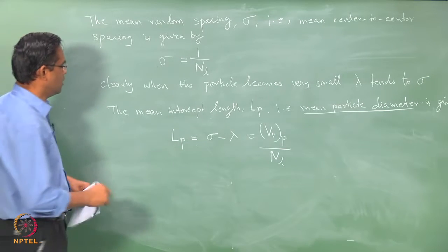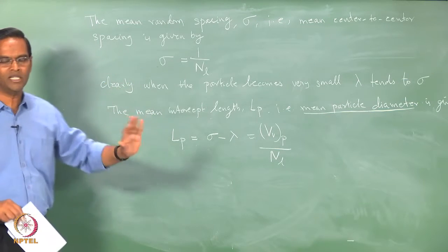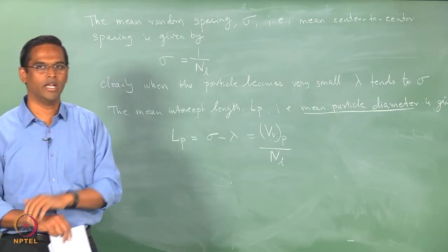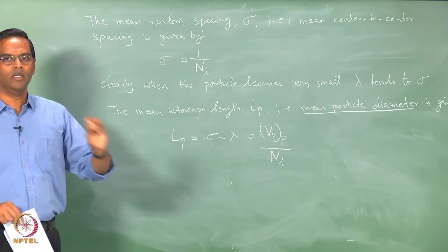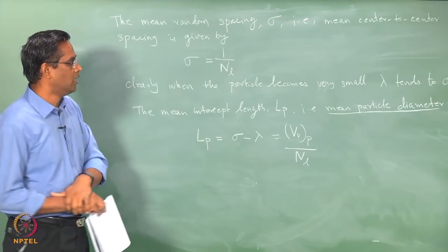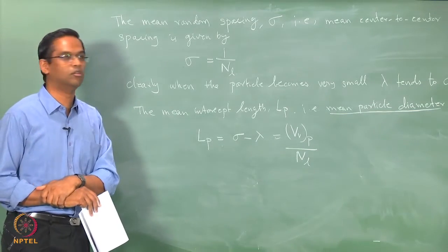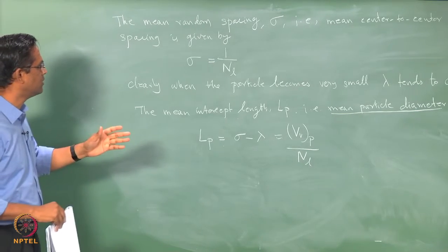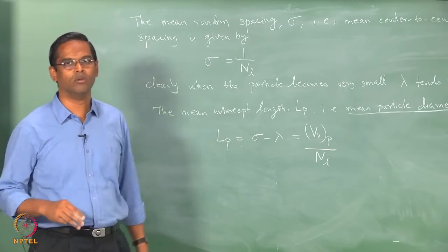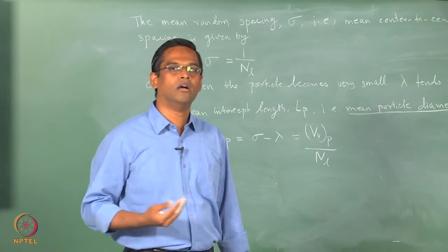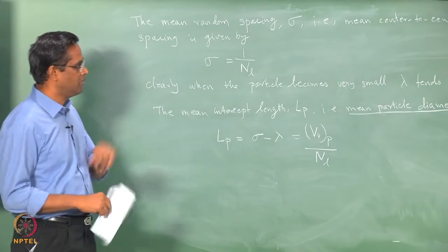So, what we are trying to say here is that simple measurements from an optical micrograph or any photomicrograph, a simple point counting or a line intercept counting, will give you a very effective and very powerful way of measuring quantitative parameters. They are very powerful techniques. So, one has to just appreciate and realize this. I will show some of these expressions used to evaluate the quantitative data from a simple optical micrograph or an AFM micrograph in the coming classes.